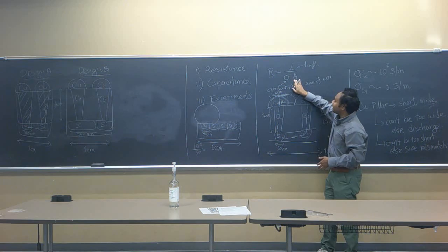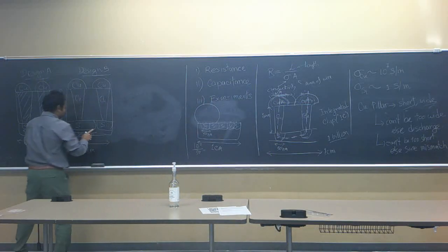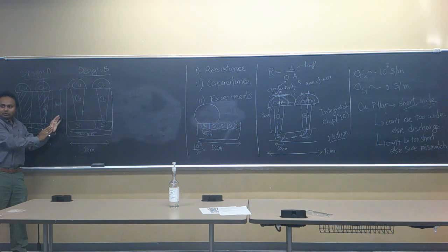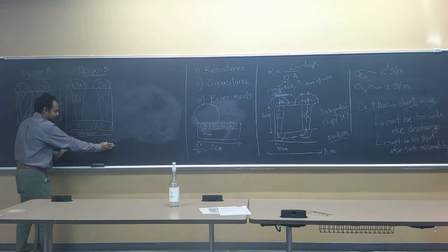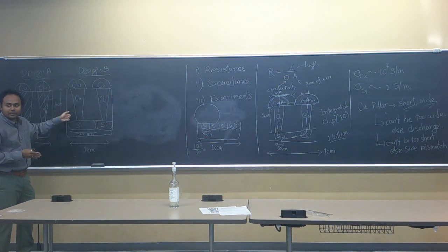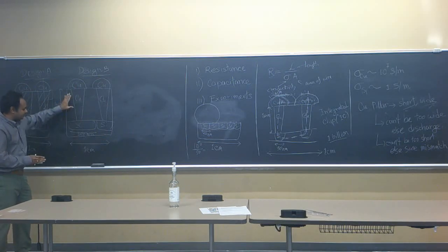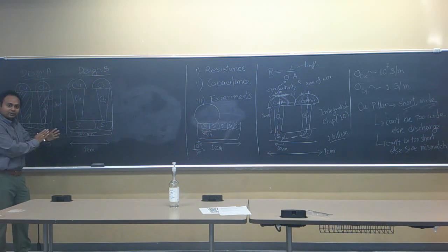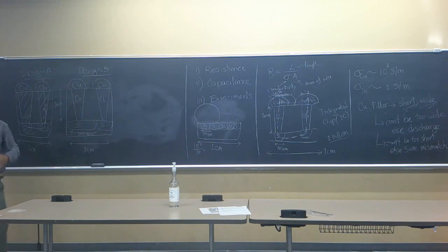Now, if you make the area very wide, that's also one option. The silicon device could be very, very wide. That's also one possibility, right? We can make the silicon device very wide, so it has two dimensions, 1 centimeter in this dimension, and the other centimeter in the direction into the plane of the board, right? So we can make the silicon device very wide so that it has less resistance. But the problem is, if you make it very wide, you won't have enough space to put more silicon devices. And remember that the performance of the processor always depends on how many silicon devices are there.